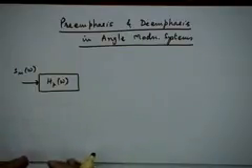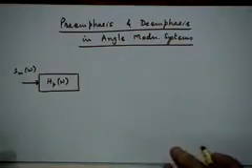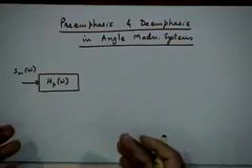But you want to do this filtering sometimes to take into account certain facts that we know about the communication system. For example, the communication system may be better suited to work with either higher frequencies or lower frequencies of the message signal. So suppose it performs poorly for higher frequencies, then what would you like to do? You would like to enhance the higher frequencies, because you like to increase the SNR of the higher frequencies. The pre-emphasis filter will be able to do that. But in the process, you're going to distort your signal.